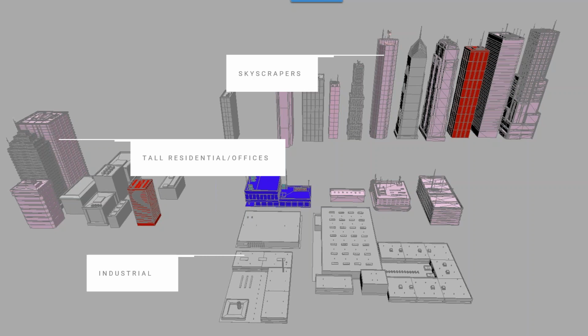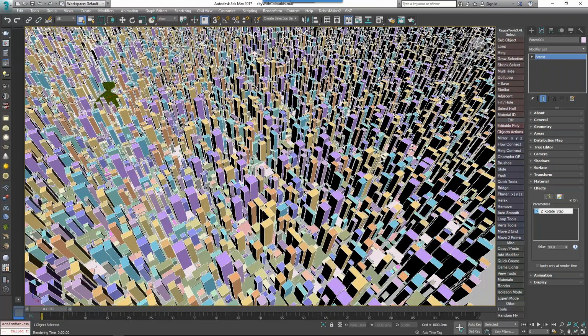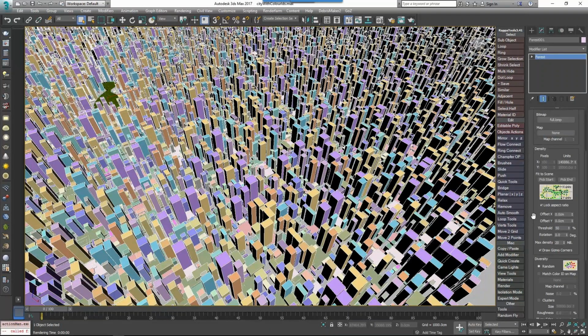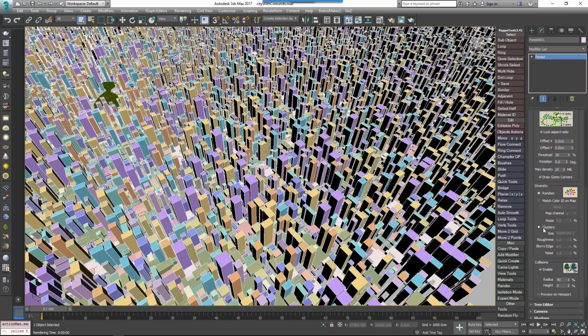What we want to do is place those, but not necessarily paint them manually, because that can take time, and this is just for filling in the back to mid-ground distance. So what we can use is diversity modes. Diversity modes are in the distribution map rollout that we just saw. They're at the bottom here, and by default it's on random, which is what we saw with the trees and grass and everything else.